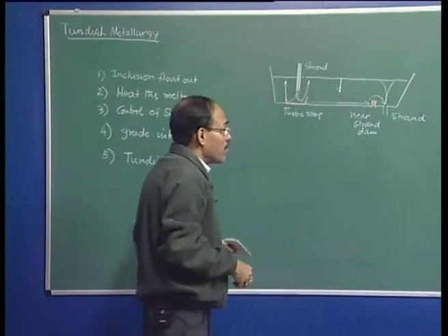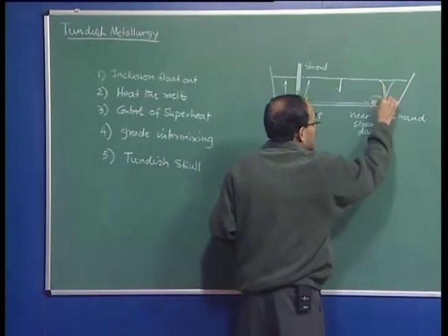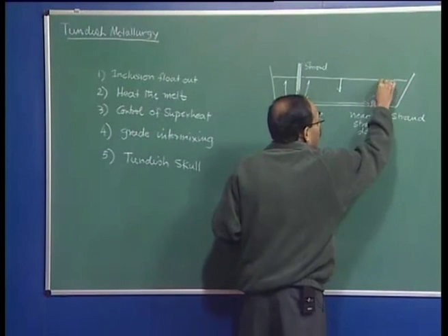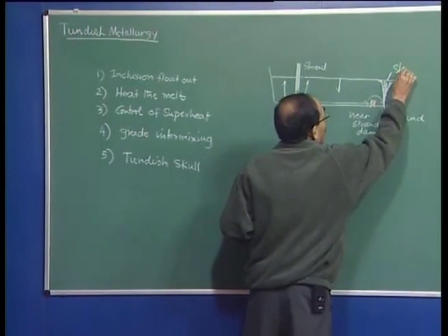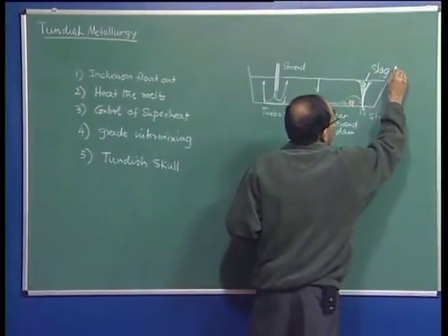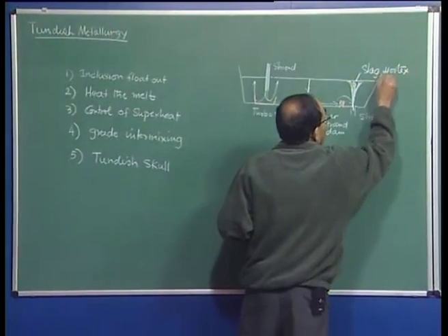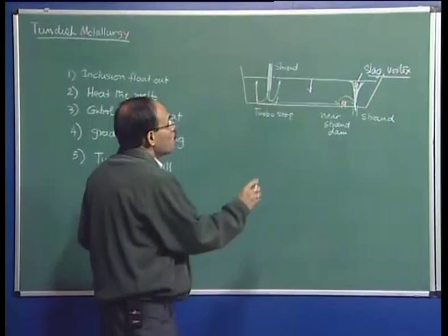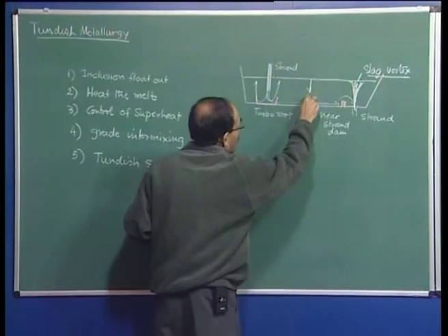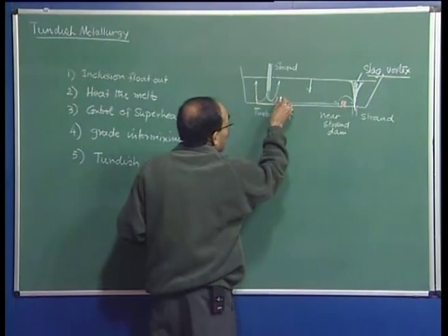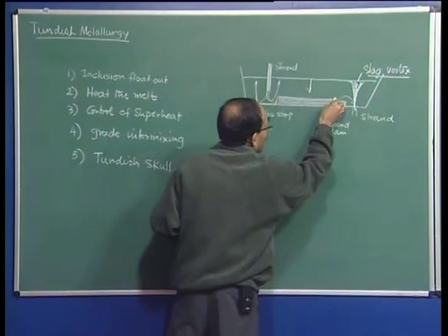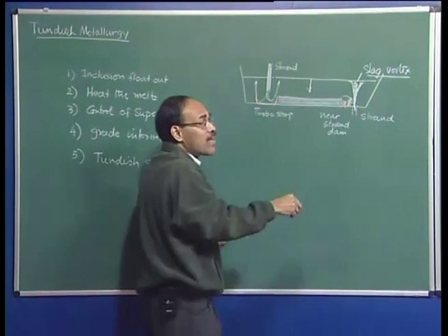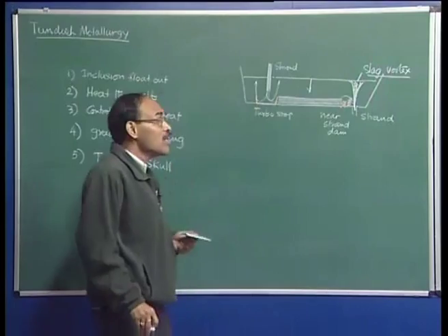and if this slag gets into the mold, then we have a lot of problems in terms of breakouts in the mold and so on. So, therefore, as the level drops below a certain level, we cannot drain the molten metal, we have to stop the casting, and this much molten material is going to be wasted.